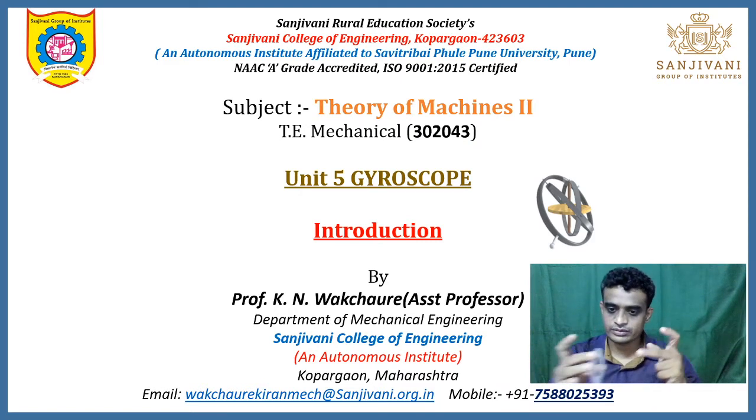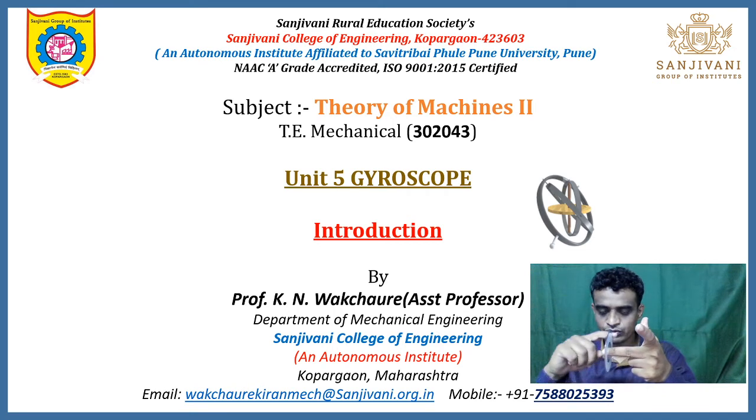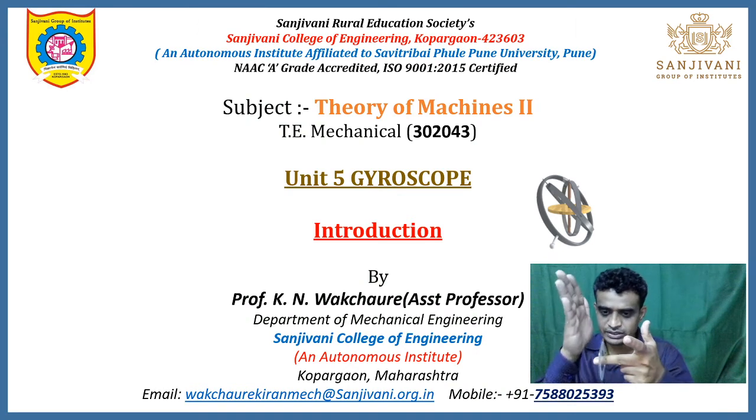This is one rotor, which is the rotary mass. This is the disc now. But just try to understand. This is one disc having some mass and having some angular velocity. That means it has some mass moment of inertia. Now what happens when this body rotates about its own axis, like this? Because of the conservation of angular momentum, that body tries to remain in the same plane of rotation. That means every time it tries to remain in the same plane of rotation.